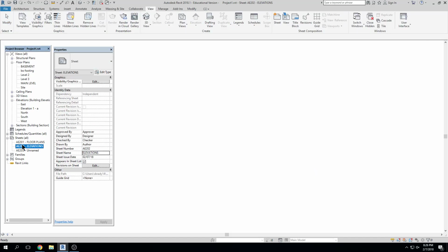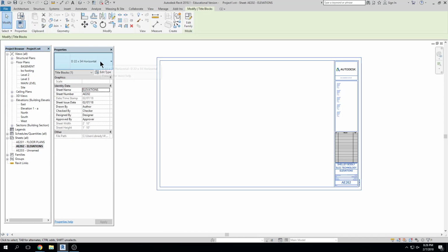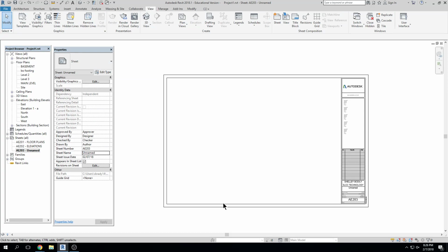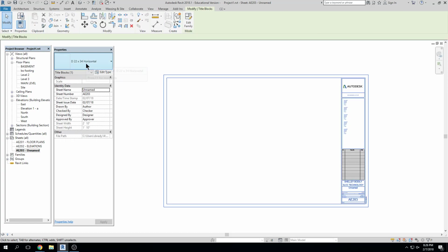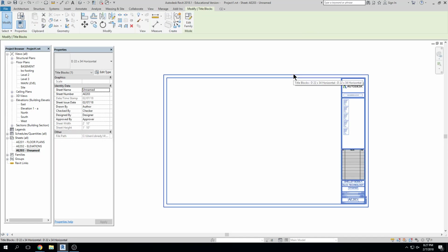And you have to pay attention to the sizes because it's not super common, but on student projects, a lot of times I think you just don't pay attention to the size of title block. You go to make a new sheet and you just put that default 30 by 42 and it's great, but maybe the assignment says 24 by 36 and you lay your nice sheets out with the scales all appropriate for a big piece of paper and then you need to put them on a smaller piece of paper. There's a lot of rearranging you have to do, right? So just pay attention to whatever size it is.